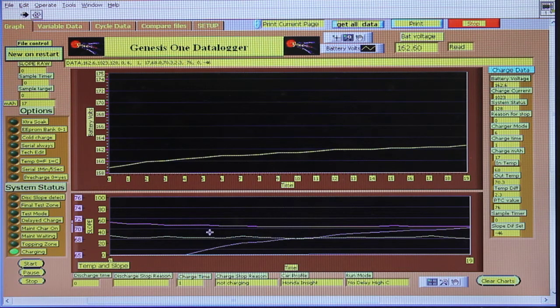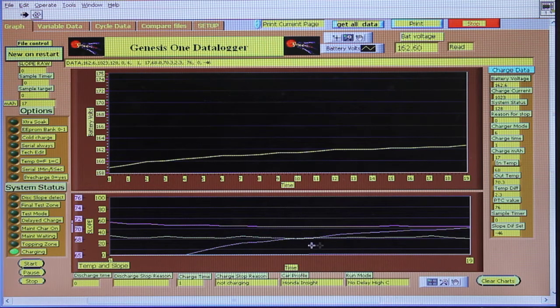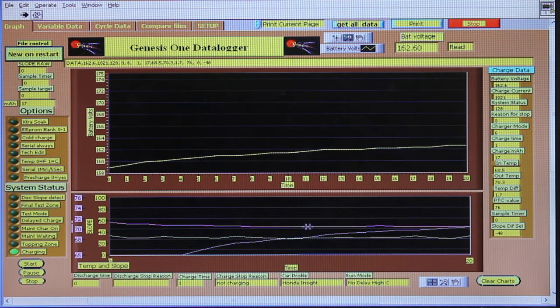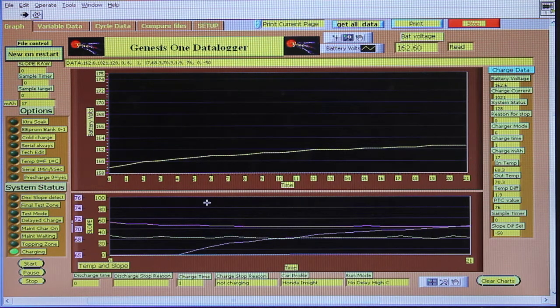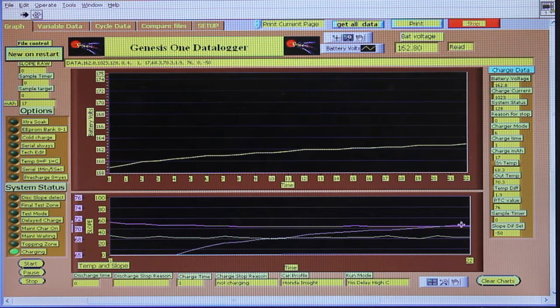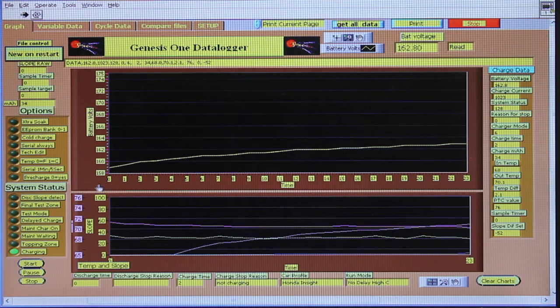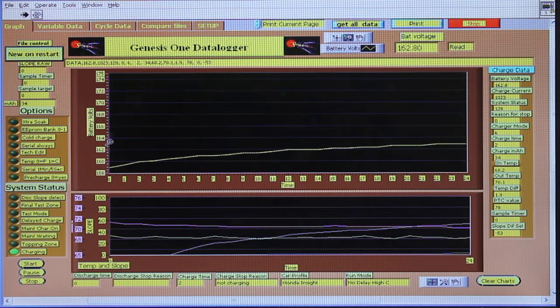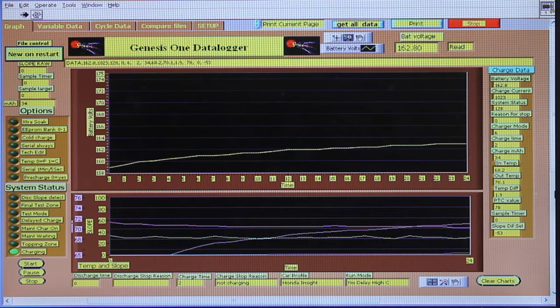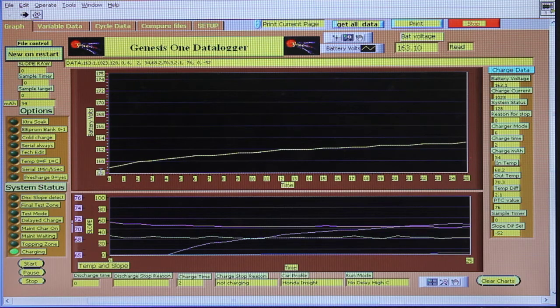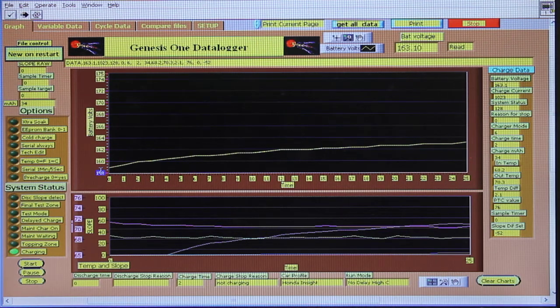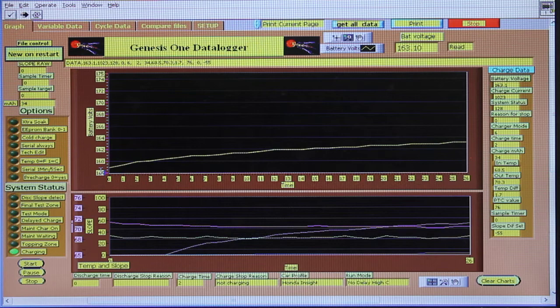Now, let's go to this gray line here. This is basically a very interesting, this is the rate of change. The higher this number, the faster the voltage is dropping or rising. And this gives you a very good idea of capacity of the pack. If you see a pack that discharges and goes way up to 130, 140, especially if it's in the linear portion, which is usually around 150 or so. And let's just expand this scale a little bit more. So we go to 140, 145.